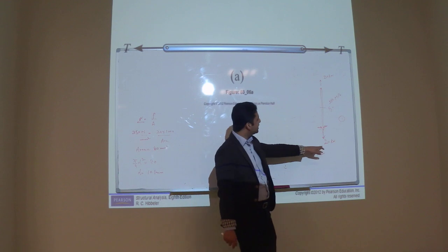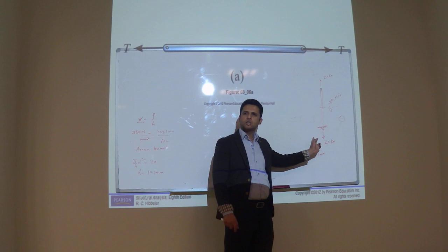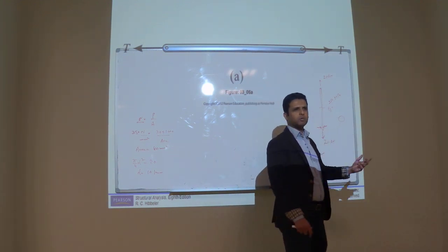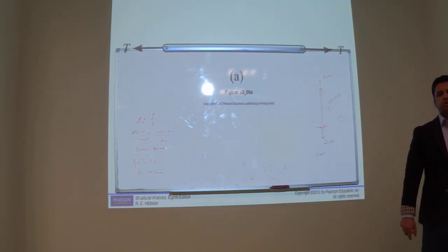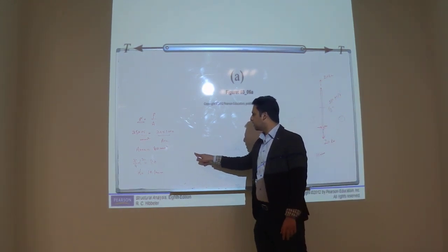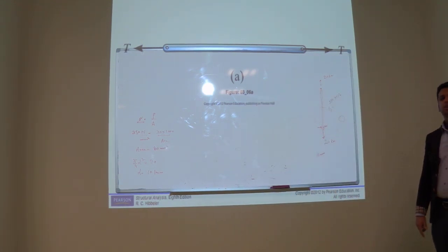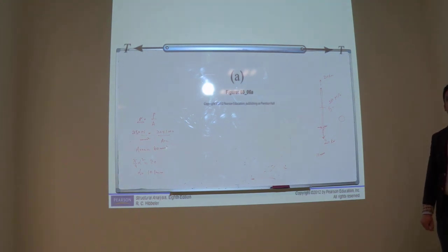So this load is what type of load? Tension load. So it means that if you want to provide a square bar, how much would be the size of the square? Just take the square root of 80. It will be 8.9.